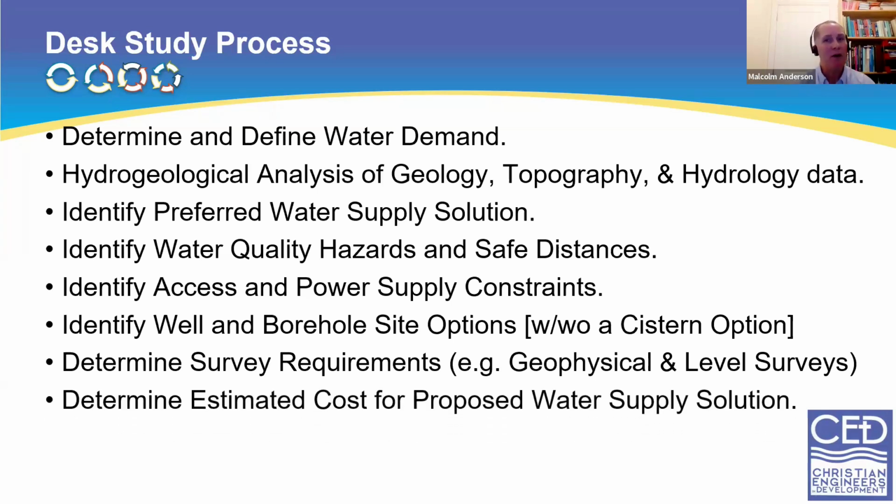Now, I haven't talked very much about cost in this, partly because of the time available, but each of those water supply solutions has a cost tag attached to it, and one of those will be the cheapest and the most reliable, and with the best resilience. Groundwater solutions provide all of those, but the risk is in the construction in the first place, because until you've actually constructed, you don't know what water quality you're going to get, and you don't know what water capacity you're going to get.